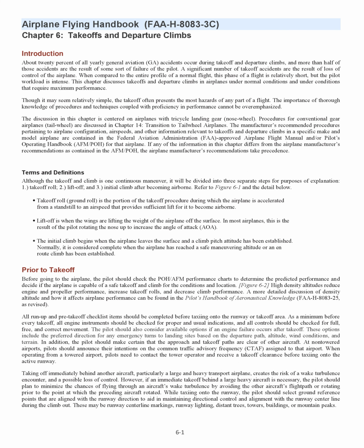All run-up and pre-takeoff checklist items should be completed before taxiing onto the runway or takeoff area. As a minimum before every takeoff, all engine instruments should be checked for proper and usual indications, and all controls should be checked for full, free, and correct movement. The pilot should also consider available options if an engine failure occurs after takeoff. These options include the preferred direction for any emergency turns to landing sites based on the departure path, altitude, wind conditions, and terrain.